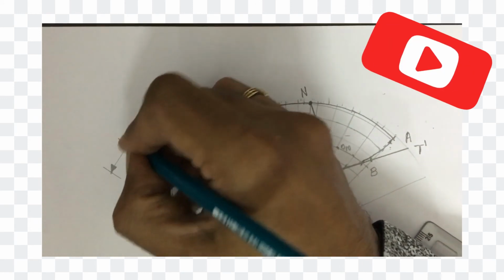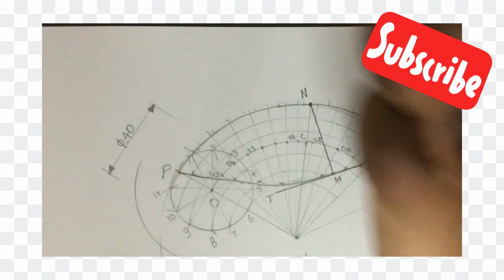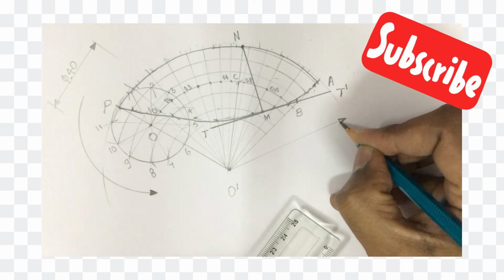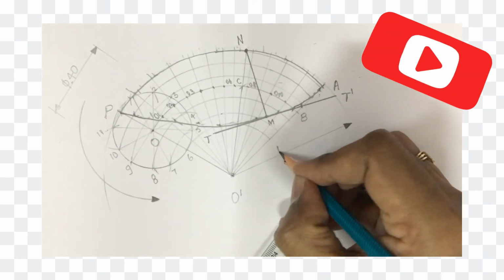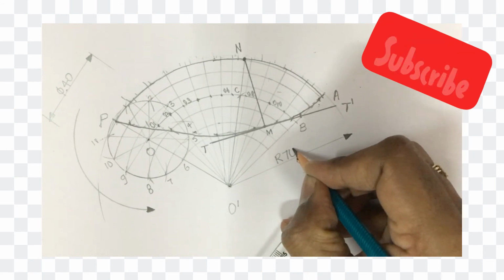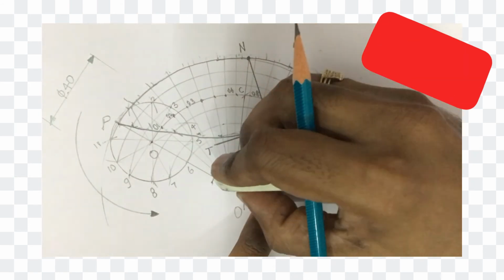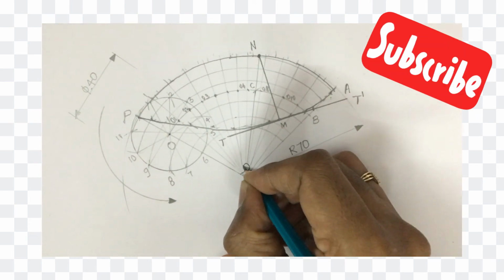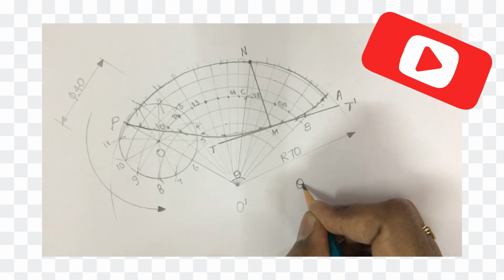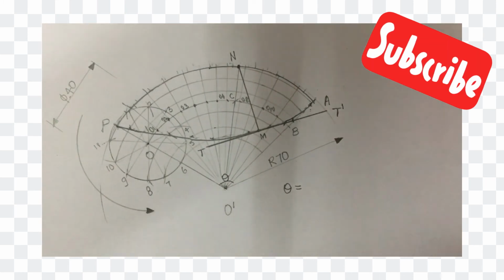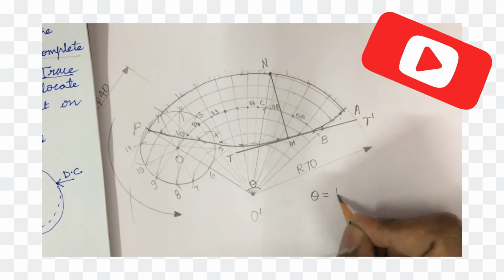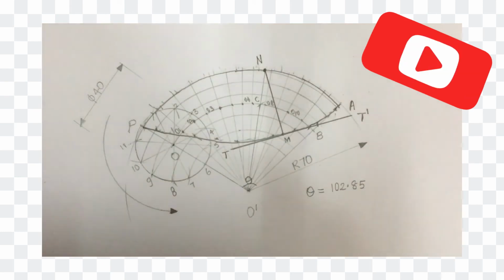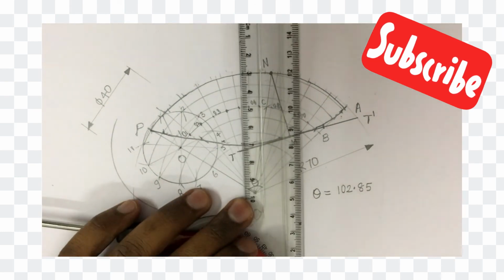So this is given as pi 40, dear students. Your handwriting to be very neat. And this I have taken to locate the radius of the directing circle, that is given as R70. And do not forget to write the value of theta here. So make a neat arc and write theta here and write the value of theta to be as we have worked out. This is 102.85. This is how you are supposed to work out, and try to put this theta in the box.